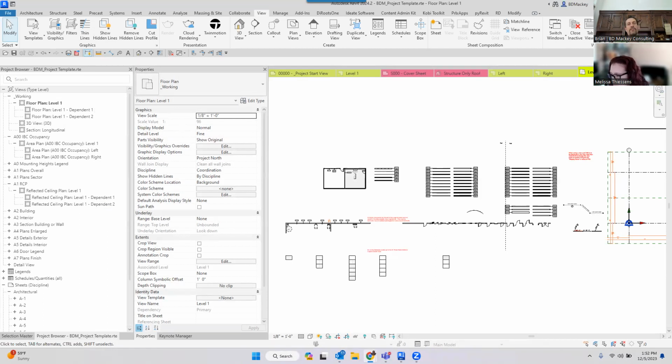But also understand that if you do set those up as an attachment, when you send your file to somebody, or if they're looking at your file, they also have to have permissions to the nested files as well. One of my clients set up their BIM 360 site and had the nested links under a different folder than the parent that nobody had rights to read or view. So it was like, cool, you got them as attachments, but we can't currently see those. So you have to make sure you're giving everybody access to those files as well.